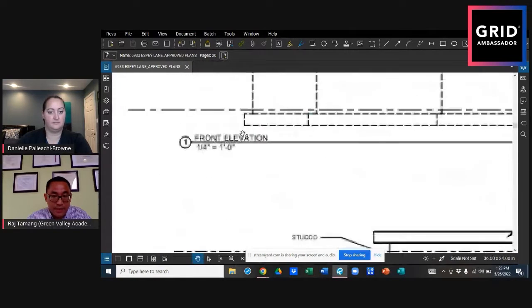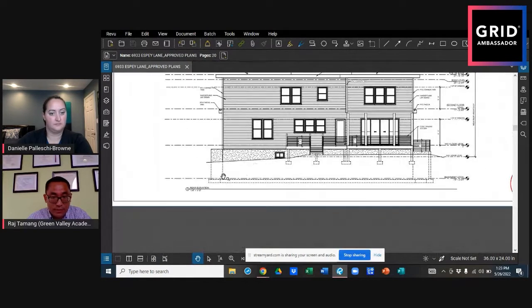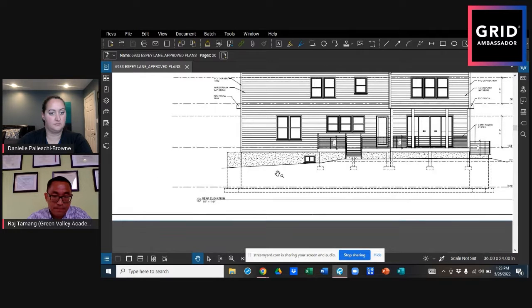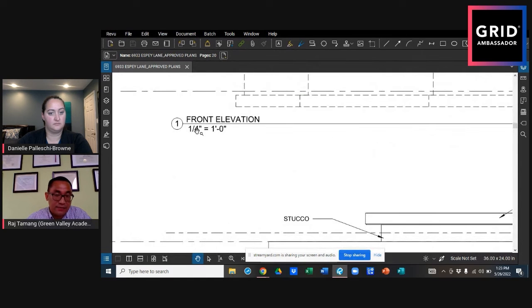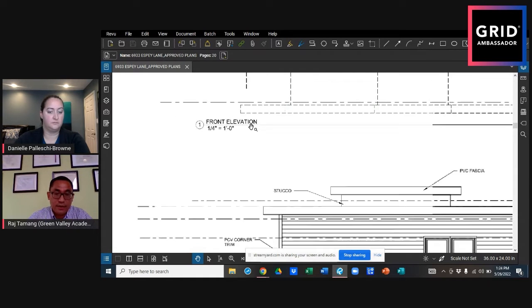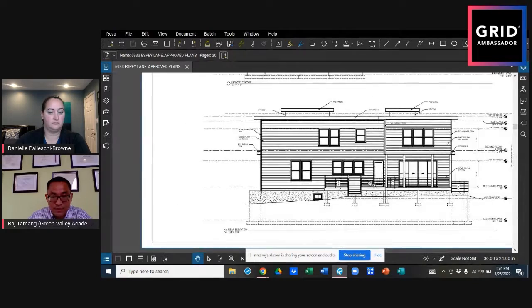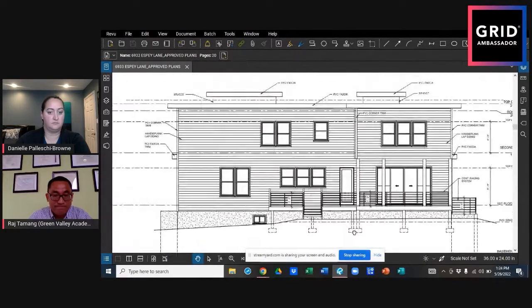And I'm calling out front elevations. This one is the rear elevation, back. And also I'm showing the scale, okay? This is very important. You have to indicate the scale you drew on this floor. These plans are 24 by 36 inch. So 36 inch wide, 24 inch height drawings, in scale quarter inch per foot, right? So if you look at the back side of it,